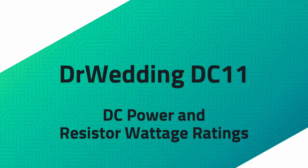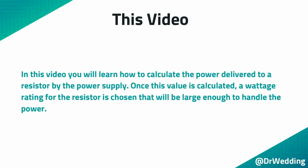DC power and resistor wattage ratings. In this video, you will learn how to calculate the power delivered to a resistor by the power supply. Once this value is calculated, a wattage rating for the resistor is chosen that will be large enough to handle the power.